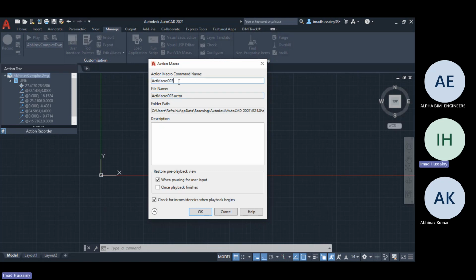If it's not working after that, under your file menu you give act, meaning it will work as a macro file. So it is the extension for this macro file. It will take it automatically, you need not worry about this. Why I'm saying this: it is saving at a particular location, in this particular root folder, and nobody is going to disturb it. If somehow it has been changed to .dwg or something else, someone has done it manually, at that time you can change this one.